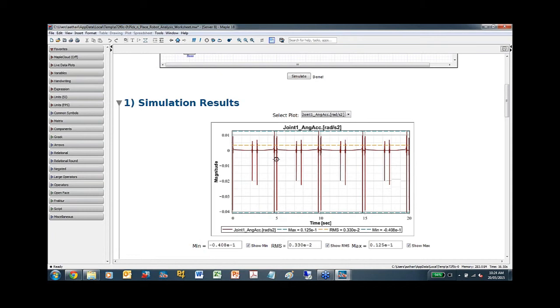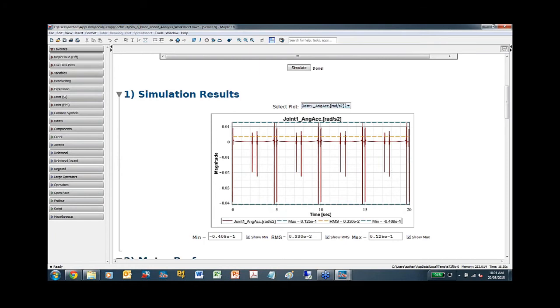For example, here you can see these high spike regions in the acceleration, which might be a good target for the machine design process, and maybe you want to start investigating this and somehow smooth out these spikes by changing the configuration of your robots, or either the way you are actuating those revolute joints or bearings at that point.